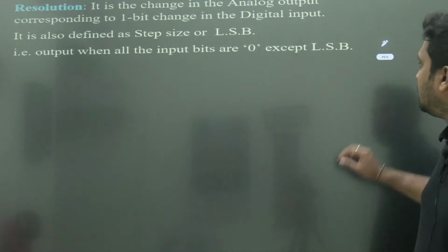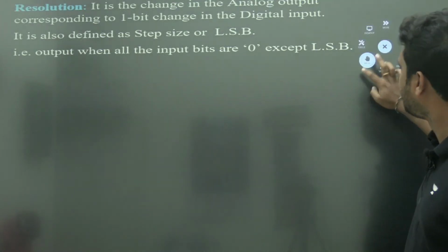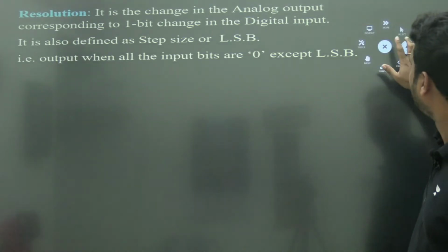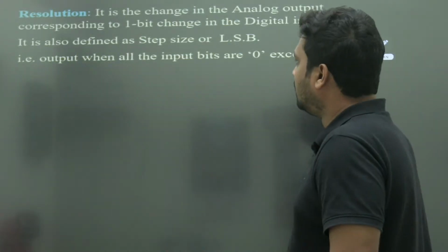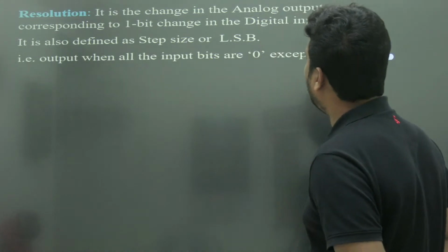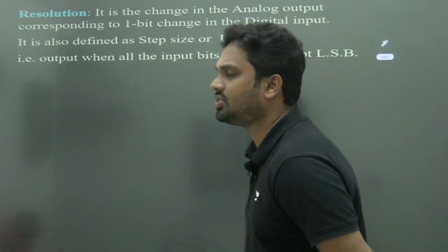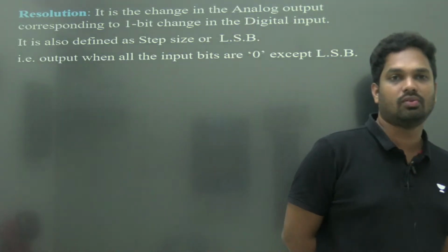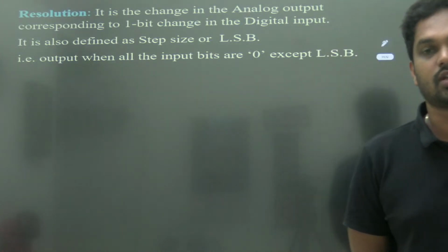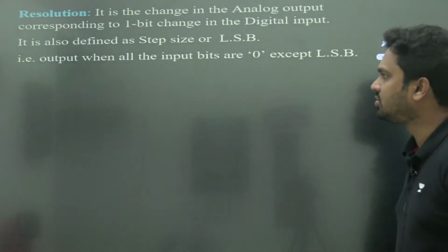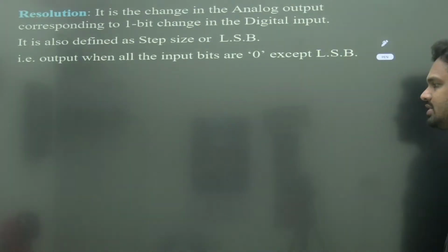So resolution is given by the change in the analog output corresponding to one bit change in the digital input. If the input is changed by one bit, the output change is given by resolution. It is also defined as the step size or LSB. It is the output when all the bits are 0 except LSB.